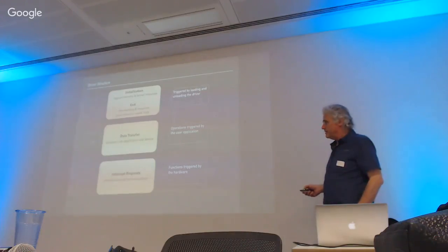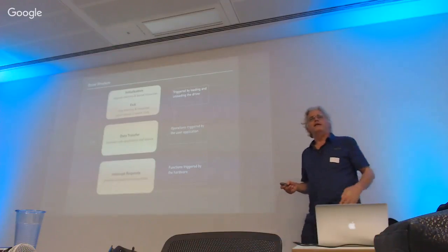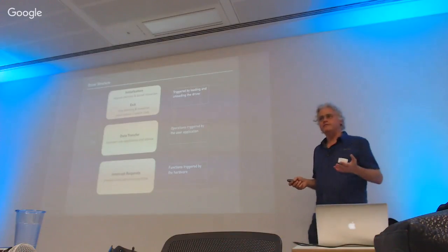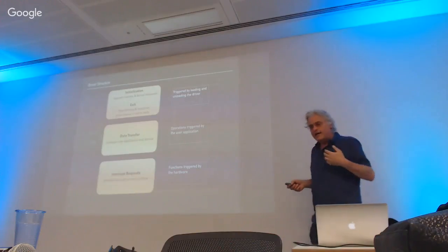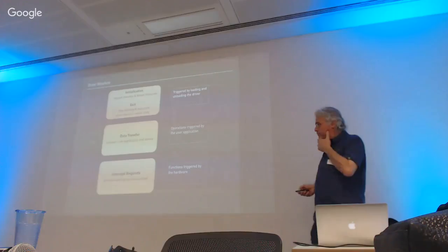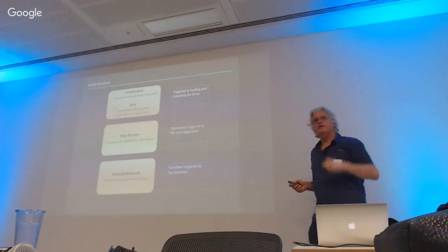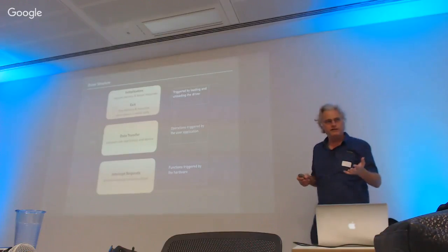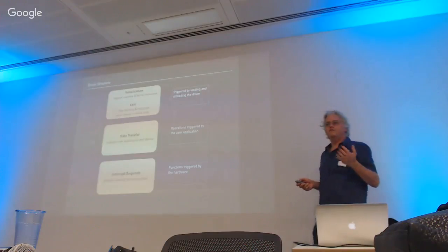And as soon as you can set an alarm condition as an interrupt request, for example, and then the interrupt request will generate some sort of service routine and deal with that alarm. If you wanted to send these interrupts up into user land where your application normally runs, you don't quite know when that interrupt is going to be handled or serviced. Any sort of process that's running up in normal user space, the timing of that is always under the control of the kernel.